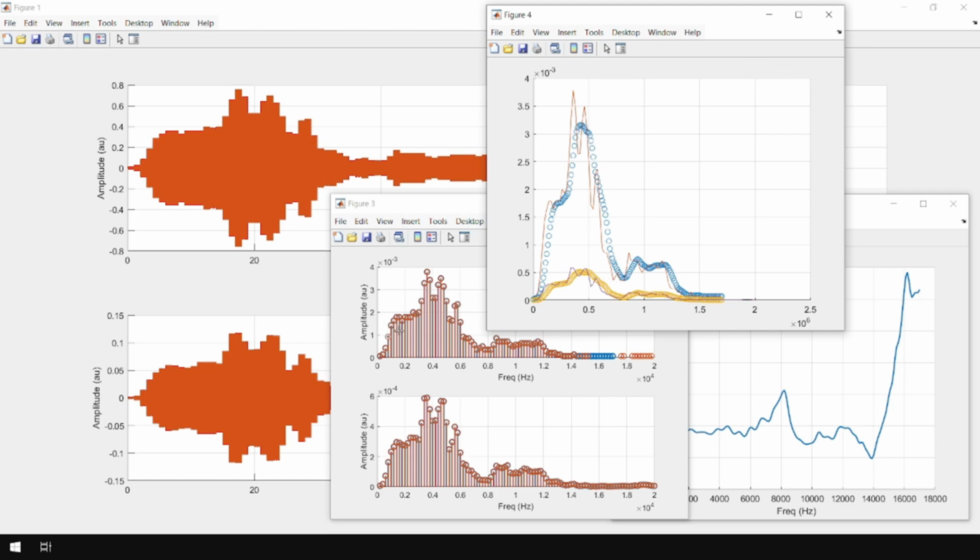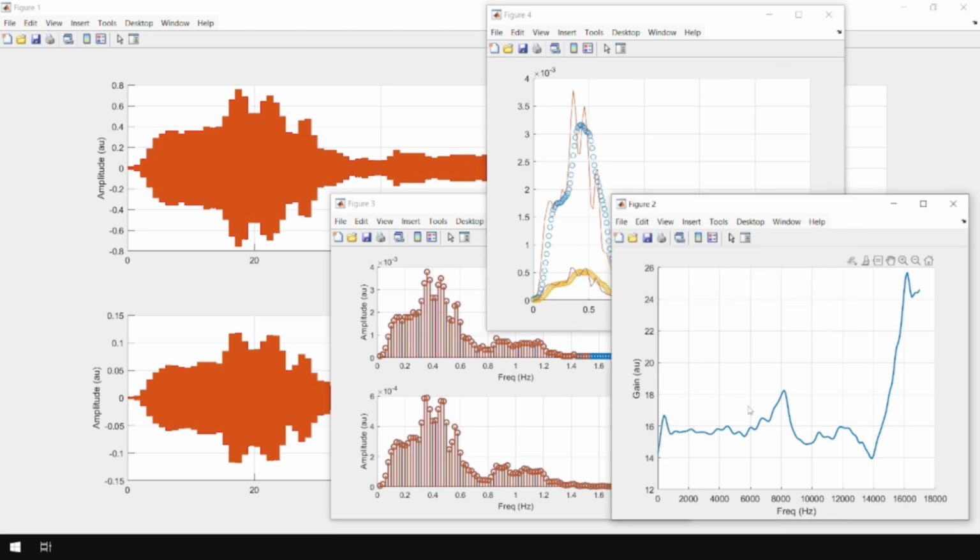The peak alignment algorithm was very successful. You can see we had problems with the low signal, but nevertheless I'm very happy. This peak alignment actually has restored them. You can see there's some delay from the filtering, but nevertheless I'm very happy that it worked at all. We can see we have around 15.75 dB in this flat section here. Interestingly, it peaks at 18, so I wonder if the true response is something like that, and then it dips off.